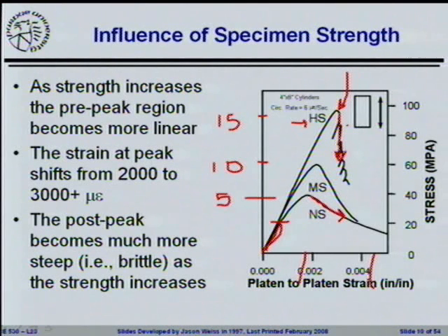But if you remember, you start off and you start doing your calculations, and you have to determine these coefficients for the Whitney stress block. There's an alpha coefficient and a beta coefficient. And if the concrete strength is greater than 6,500, then alpha is 0.6 or something like that. Right? And there are all these different rules. Those rules are their best way to make the Whitney stress block work for these stress strain behaviors. That's how they're accounting for the brittleness in these particular materials. Okay? That's where that's coming into the code.